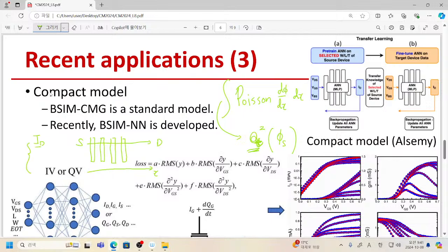It means that you can generate a drain current model, source current model, even gate current model, and if you have a substrate, then you can also generate a model for substrate current. So although it is much simpler than TCAD simulation, it has its own logic. Although it is simplified, why it is expressed in this way, we can trace back to the governing equation.